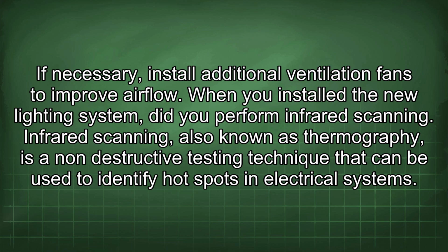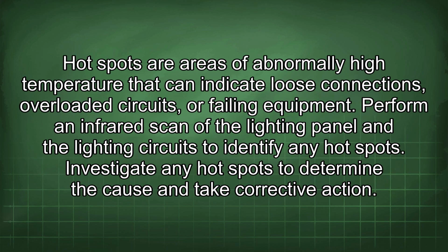When you installed the new lighting system, did you perform infrared scanning? Infrared scanning, also known as thermography, is a non-destructive testing technique that can be used to identify hotspots in electrical systems. Hotspots are areas of abnormally high temperature that can indicate loose connections, overloaded circuits, or failing equipment.